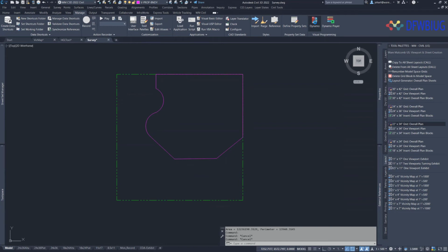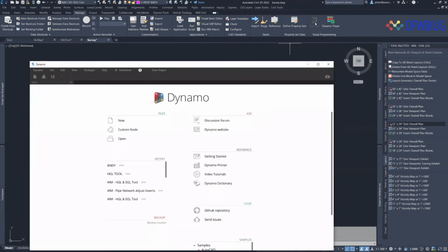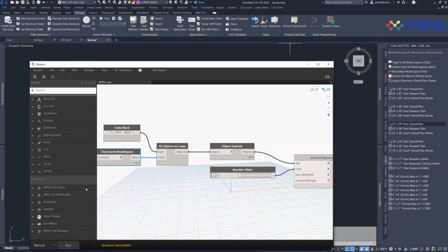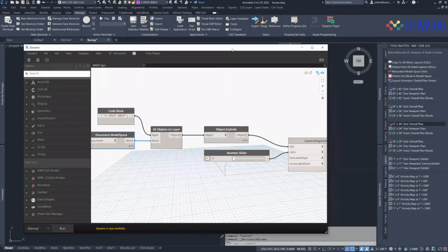So this routine is going to basically allow you to add labels for enclosed polylines, kind of like a partial label, and add the labels at the same time. So we're going to have it add the labels for us. You can have it add an area label. If you had easements in here, it could label your easements for you, your lots. We're just doing a high level here, but whatever a person would want to do, they're capable by using the script. If you do a lot of easement exhibits, for example, you could have it automatically do that and even place a dimension and put more information in there.